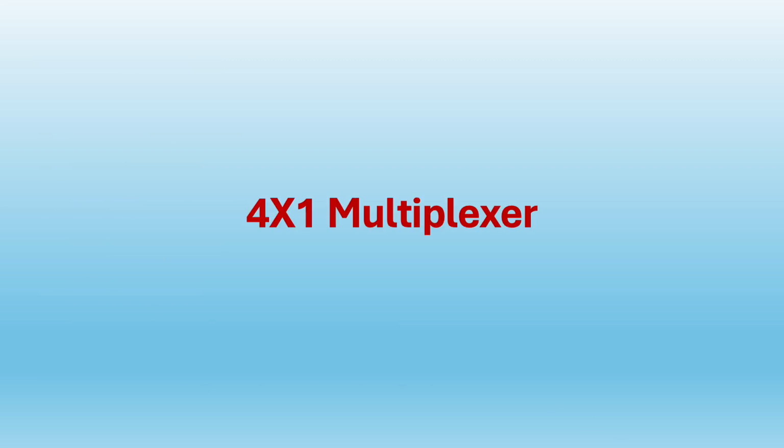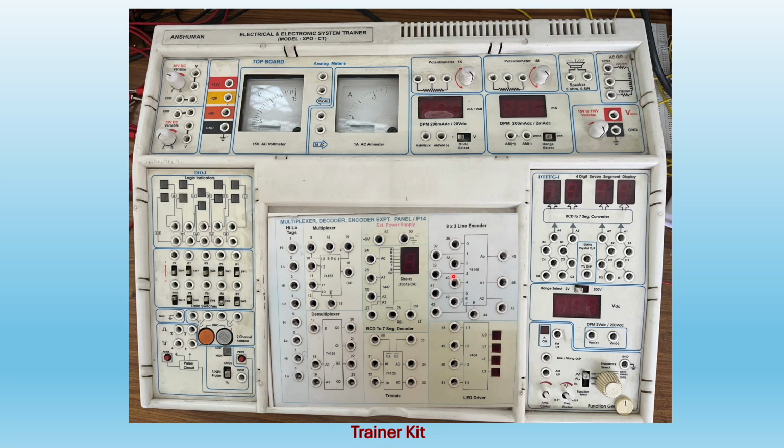Let's do the experiment on 4x1 multiplexer circuit. This is the trainer kit on which this experiment will be performed, and this is the general purpose kit on which this trainer kit is mounted. So DC supply from the kit will be connected to this trainer kit for operation of different ICs of the trainer kit. These are the input switches through which input will be applied to the trainer kit. Switches are having two position, high and low. So by changing the switch position, we can apply high input or low input to the given trainer kit.